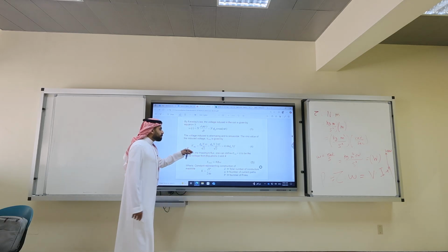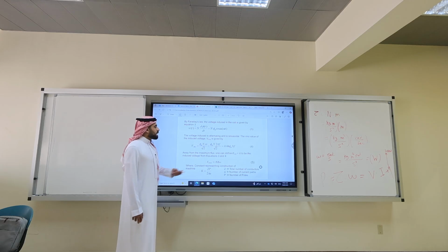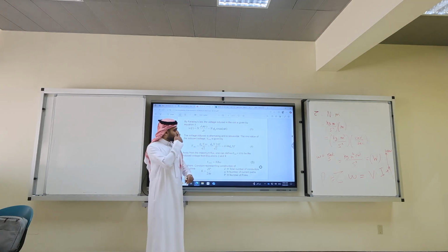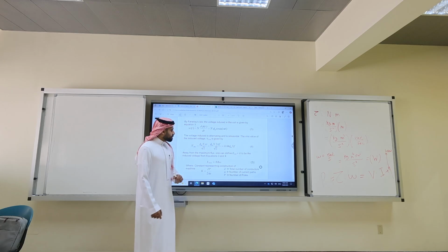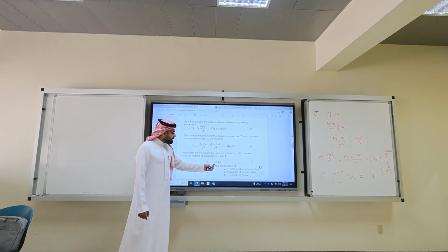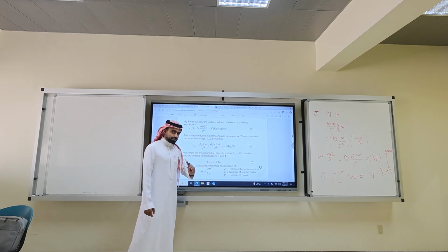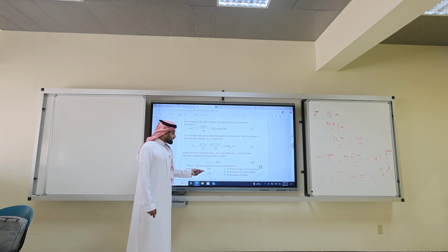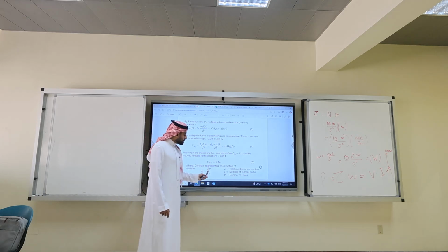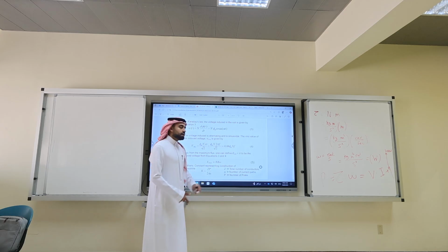So away from maximum flux, let's define this voltage to be E induced. If you combine the equations, you will have a constant K. This K is not this number, by the way. This K is a constant representing the construction of the machine. It is Z times P over 2 pi A. What is Z?